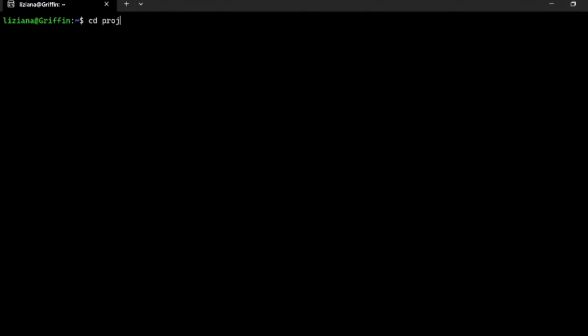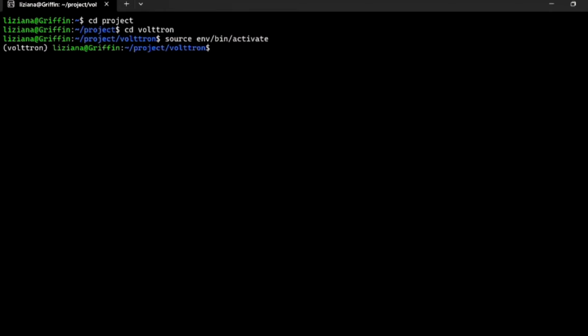On the server side, VOLTTRON manages energy data flow between DERs and the grid. The server collects data, processes it and sends instructions back to DERs. For example, during peak demand, the server can command solar panels to manage output or batteries to discharge. Simulink simulations help us test and validate these control decisions.